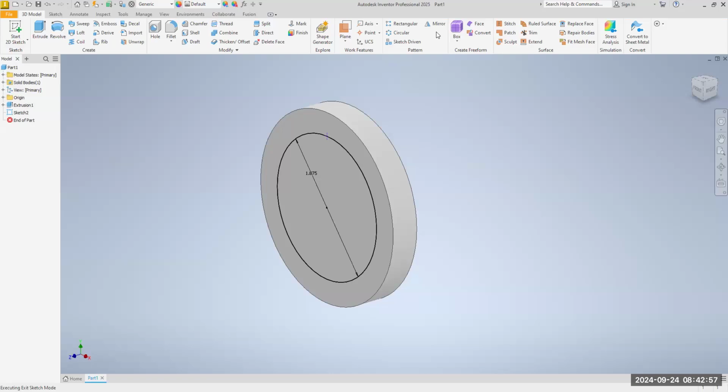Now we're going to create a hole. You've never done this before. So at the 12 o'clock position on your drawing, it says we want to put a 1/4-20 UNC-2B. What does that mean, Mr. Morris? The 1/4 means the diameter of the hole. 20 means the number of threads per inch, so we're going to make a threaded hole, also known as a tapped hole. A 1/4-20 UNC. No, it's not the University of North Carolina, as some students have put in the past. It stands for Unified National Coarse.